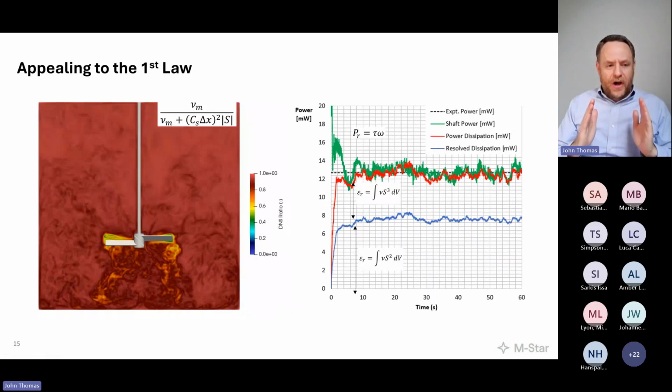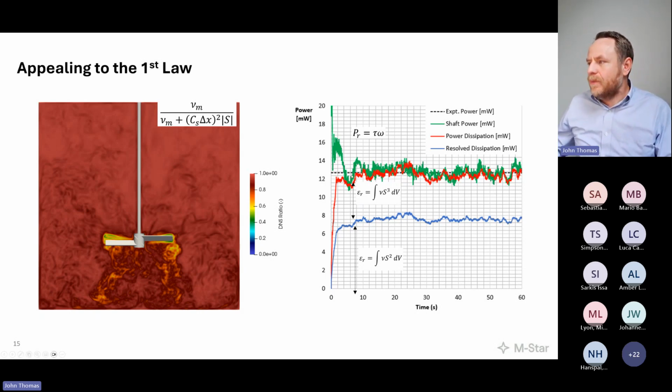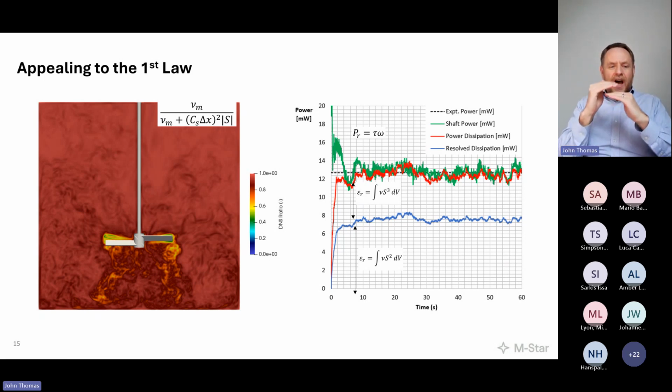Now, we know, though, with the LES filter, how much we're seeing and how much we're missing. So again, we can decompose this total energy dissipation rate into two things, the resolved and the unresolved. We can see how hard the subgrid filter is working, how much energy it's mopping up that was missed by the grid explicitly. Our grid resolution here is not sufficient to see all the way down to Kolmogorov, which means there is some component of that spectrum that is not being captured by the simulation, that is instead being captured by the Lilly-Smagorinsky model.